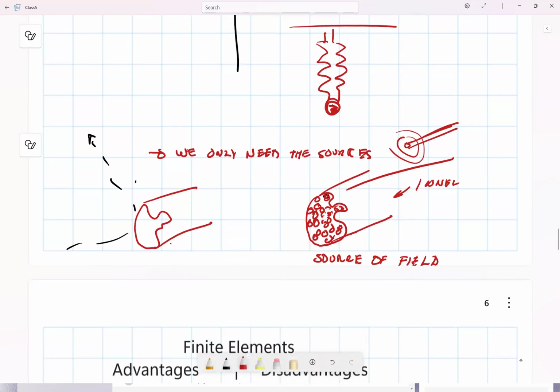So say you have this arrangement, a conductor of this shape. You discretize it into cylinders. You know the solution of the cylinder, so you just add the solutions. The people who solve this will tell you that I am crazy and that there is a lot more sophistication than that. To which I will tell them, sure, but you cannot solve anything that is nonlinear. And all my machines in power engineering saturate. So that's the end of it.